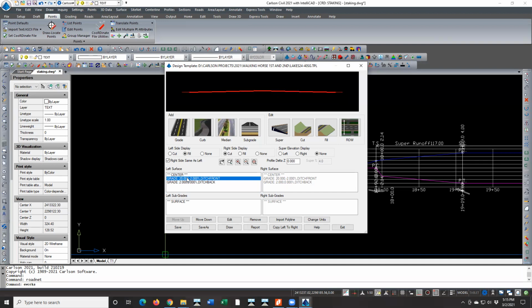So this point at ditch front, that's where it's going to daylight through that bank. Yeah, or into the bottom of it. Okay. And then we come here to the back where it's going to start up, and that's where you stop your subgrades. Is that right? And then, yeah, we don't build. Well, they build from the front of the ditch, and then they come back and dig that 2-foot bottom. That's how they do it. I personally wouldn't do it that way, but that's the way they do it.